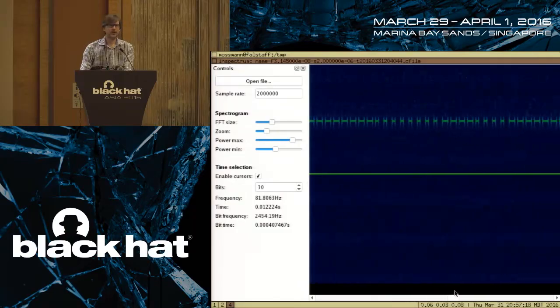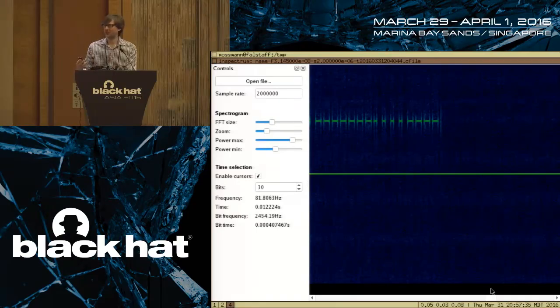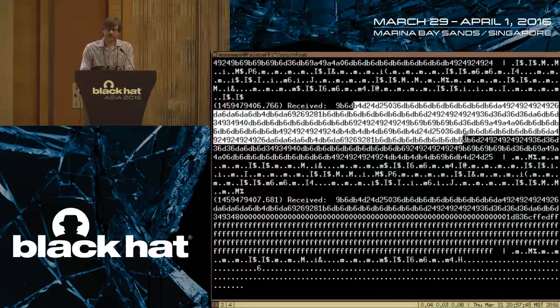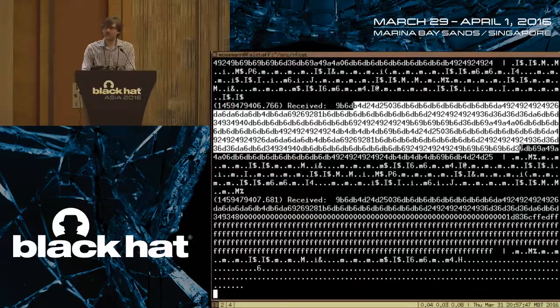And if I were to compare this, I'd probably notice that it's really transmitting the same information over and over and over again. And that's just a crude way of dealing with unreliable radio communications, right? They could use some sort of sophisticated forward error correction or something, but they don't. They just send the same packet a whole bunch of times in a row and hope for the best. That's a cheap and easy way to improve the reliability of a radio system. So it's not surprising that we see a lot of repetition here.